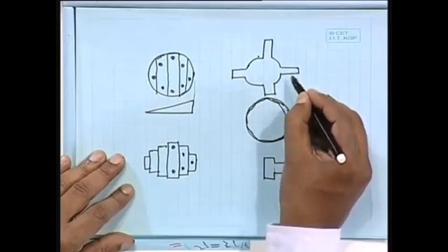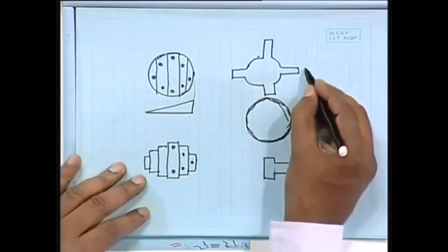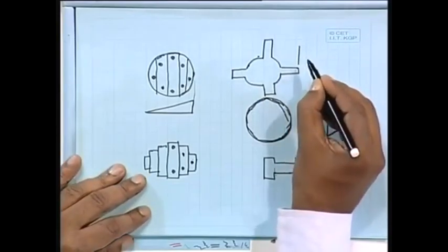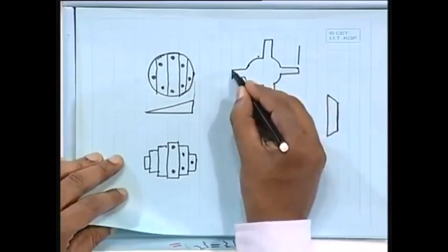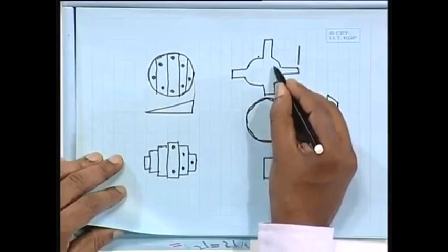What you have to do, again, you have to find out the same strain diagram as if you are having this with the maximum stress. So I can find out what is the maximum stress and this is the minimum stress, and I can find out again the interaction diagram for this curve.